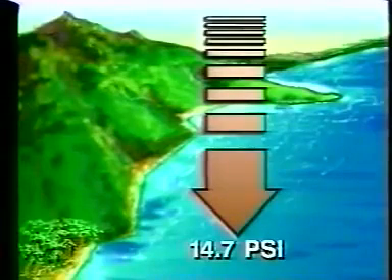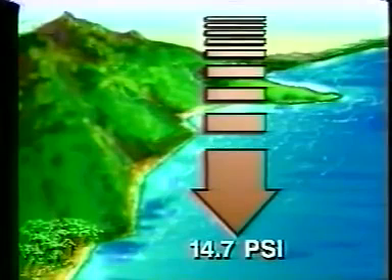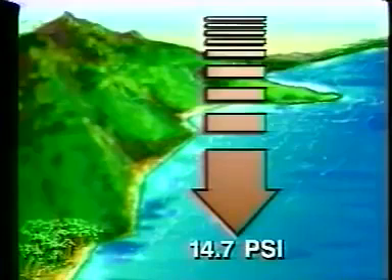The addition or removal of heat will affect the total amount of energy in the substance. This heat energy, the energy of motion, is one factor that determines phase. Another very important factor that's used to control phase in the hydrocarbon industry is pressure. At sea level, all matter is under an atmospheric pressure of 14.7 psi. Changing this pressure will result in a change in the intermolecular space. On the job, we can do this with compressors, vacuum pumps, or instrumentation controls.